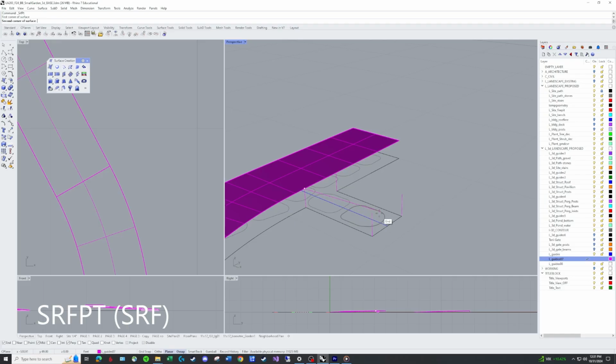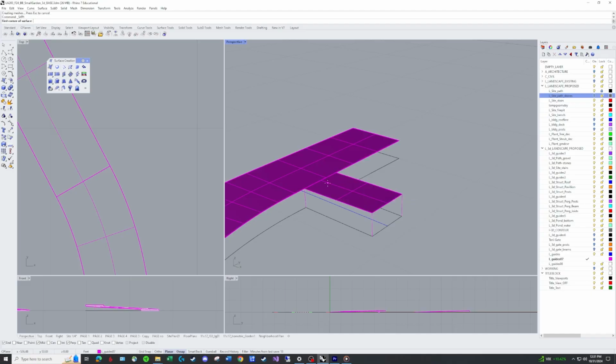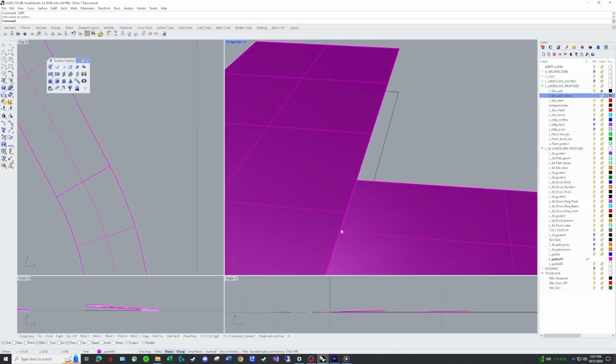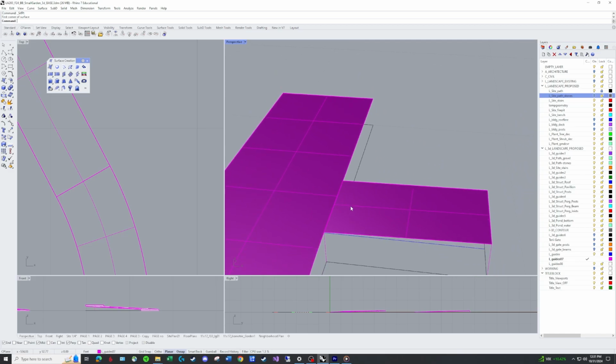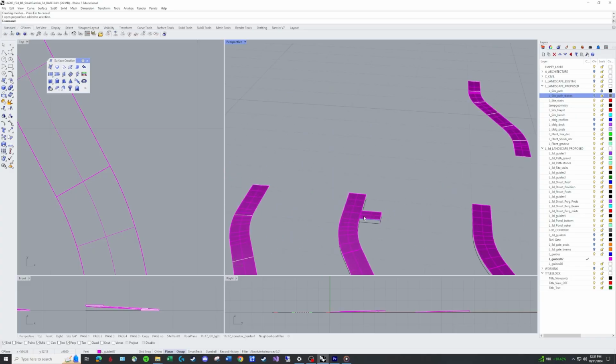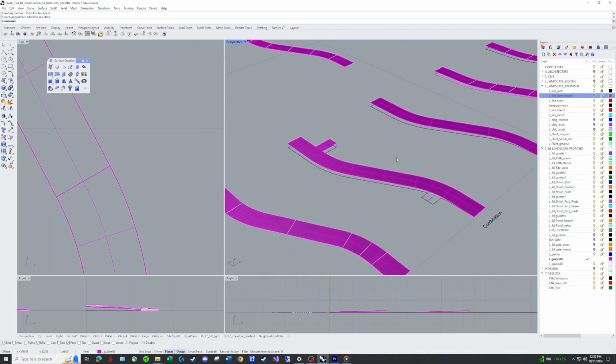And I'm really trying to avoid accidentally snapping onto these stones, but we're going to include the stones in at the end of this once we get our path going. So make sure that if you see any daylight in there, it doesn't match up. Sometimes it doesn't, even if you can't see daylight. But here's what we have to do to check it. If you join it and it joins, you're good. It's a watertight surface. You don't have to worry about doing anything else. If it doesn't join, you'll have to use the edge surface command, which is what I'm going to show you how to do next. So if that ever happens, this is what we need to do.